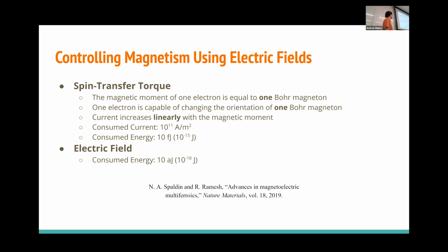But using electric fields, a typical electric field control device consumes only around 10 attojoules, which is about 3 orders of magnitude lower than for STT. And this is the main driving force behind the research effort in multiferroics.